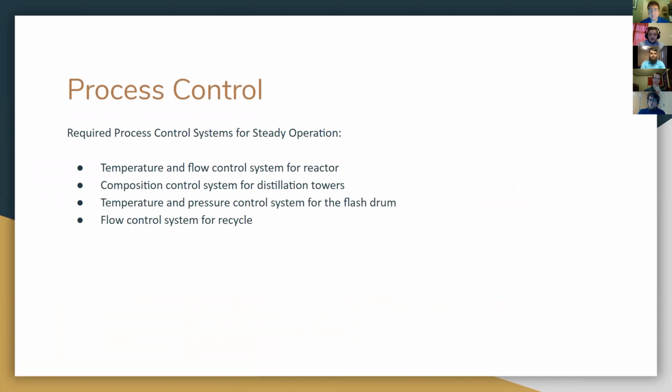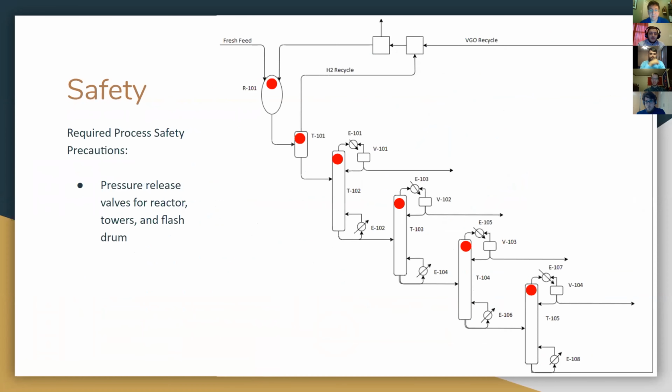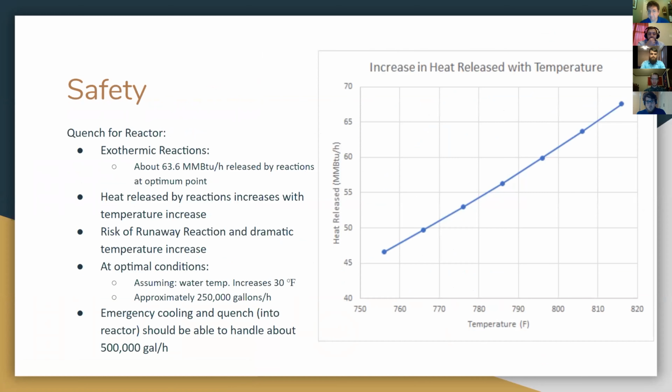I think Tyler was discussing it. Yeah, I mentioned having a quench in place. Give me this one right here. Yeah, go back. That was it. That drawing that you had with the control valve and the cooling water. Yeah, having emergency cooling in a jacket around the reactor and a quench into the reactor just in an emergency case.